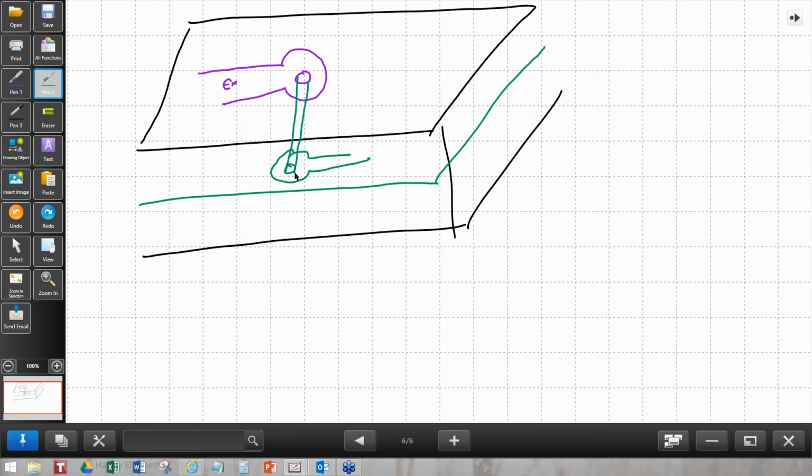Here's the difficulty. In order to do this, you need to know what you mean by optimum. As you push current down here, that current is going to be seeing some kind of resistance per unit length in the trace. Once it gets to the barrel of the hole, it is going to have a different possible resistivity, but the same current has to flow down there and then out on the other trace. One approach that is a first order approximation is to look at this trace. It has a certain thickness and a certain width, and width times height equals area. And that's on the outer surface.